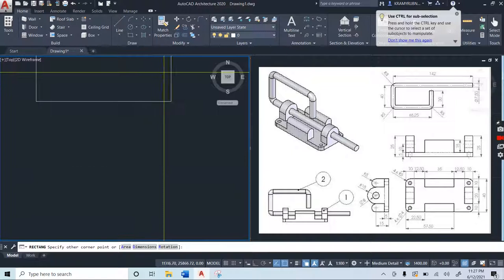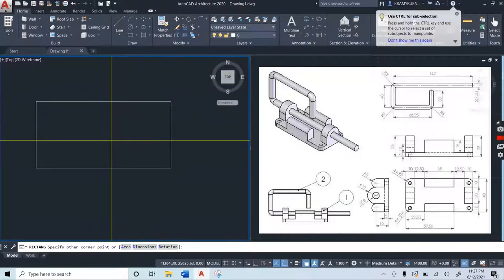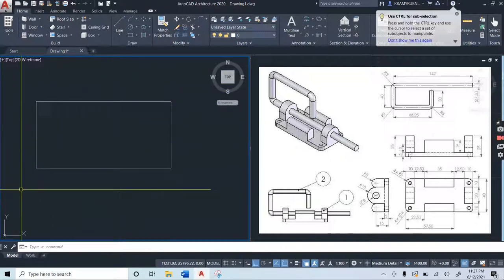Now notice a rectangle is on screen. Let's just click for placement. From our model, we realize that the 4 corners basically have fillets, and it is indicated that there are 4 fillets of radius 5. So from our modify tab, we select fillet.